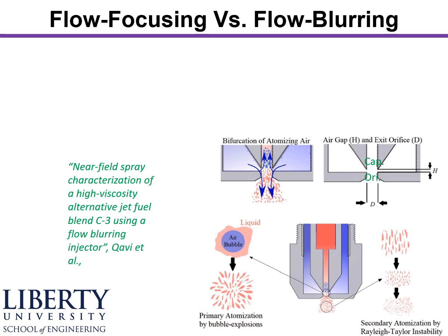upstream of the liquid, and it helps to break the liquid up. It destabilizes it, as you see in the bottom of the figure. Depending on the pressure drop across the orifice, you have a sudden expansion of an air bubble or a gas bubble inside the contiguous liquid stream, and that's going to produce rupturing and eventually smaller droplets. So that's the flow blurring scenario.